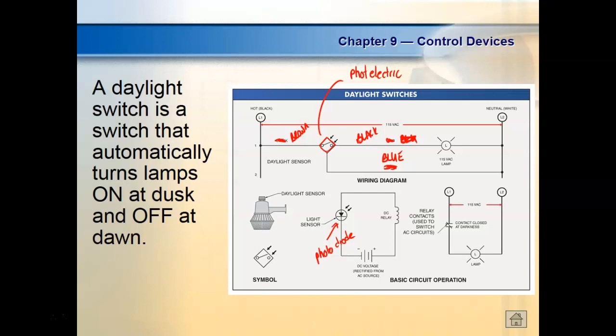So we can look at any 3-wire sensor we got, and these are solid state, which means they'll never drop to 0 volts. Anytime you see that diamond, it usually means it's a solid state sensor. There is one exception to the rule, but we'll talk about that when we get in there.